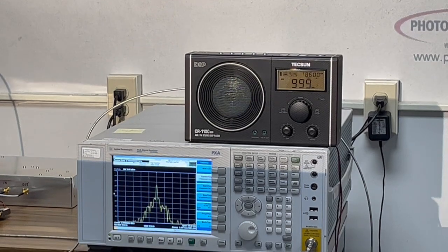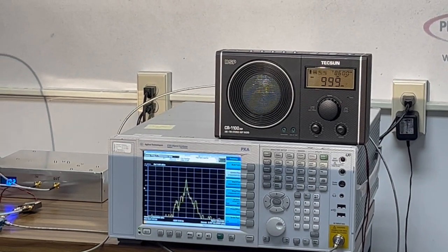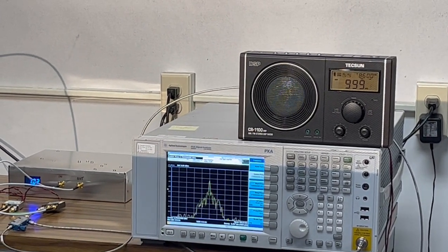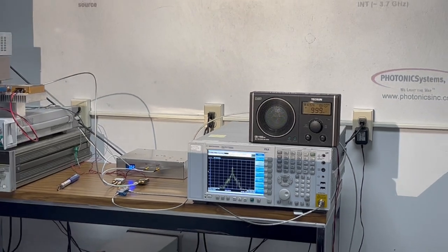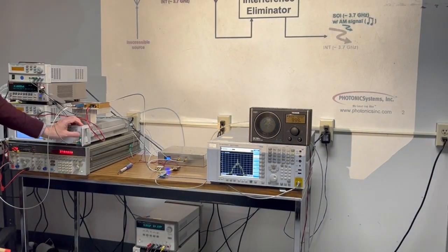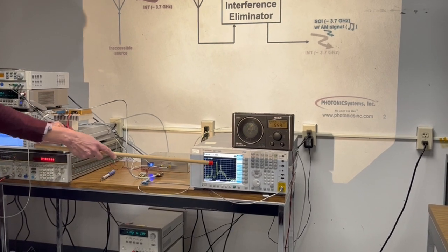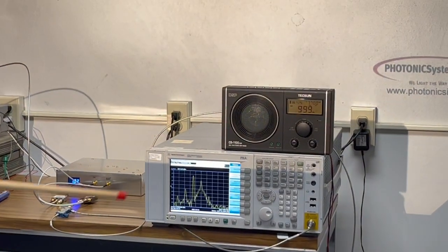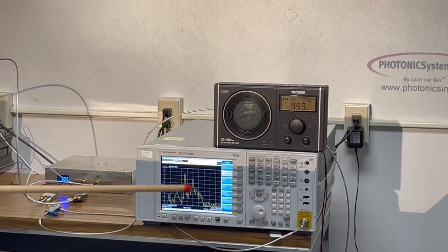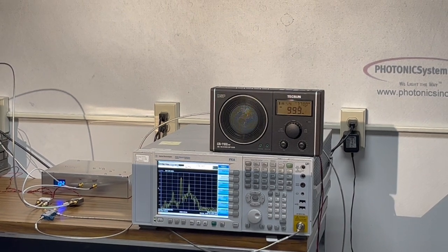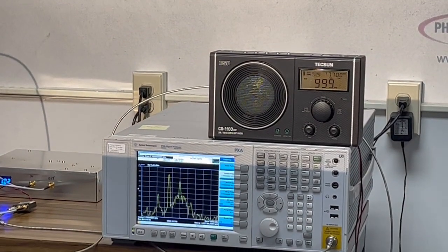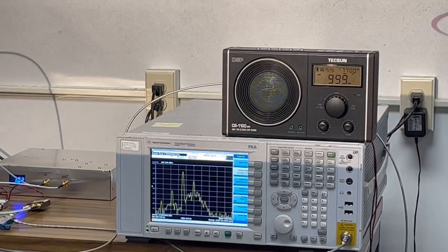There we go. All right, now the next thing I'm going to do is add an interferer. And let's see, when I add that, first I'm going to start with an out of band. There we go. It's at plus 5 dBm. It's stronger than our signal of interest tone, and it's on AM modulation, but it's outside the band, the channel of the radio right now.